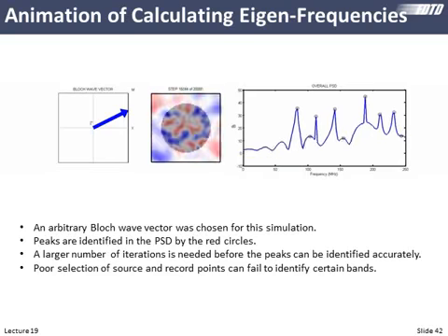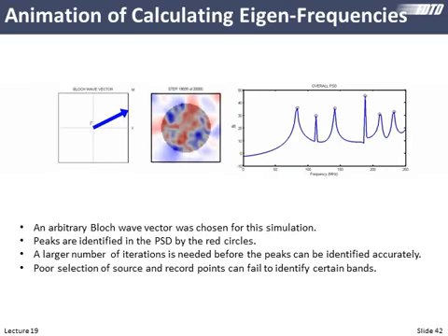So there's sort of a non-linear step in time. It started off slow, and then it's going faster and faster and faster. So you'll see the spectra evolve. But don't expect your simulations to be like this. Again, there's non-linear time steps here. But we just keep running and running and running. This is a windowing thing. The spectra we're looking at is essentially a blurred version of the real spectrum. And so the longer we run it, the more finely we can resolve those frequencies. So that's it. And we have our eigenfrequencies now after we've run it a certain period of time.